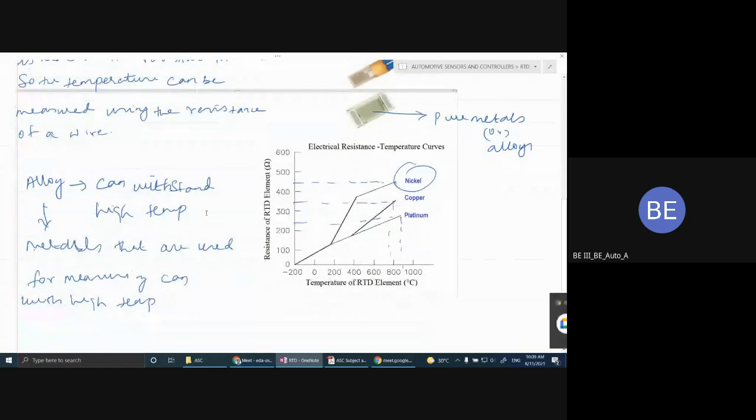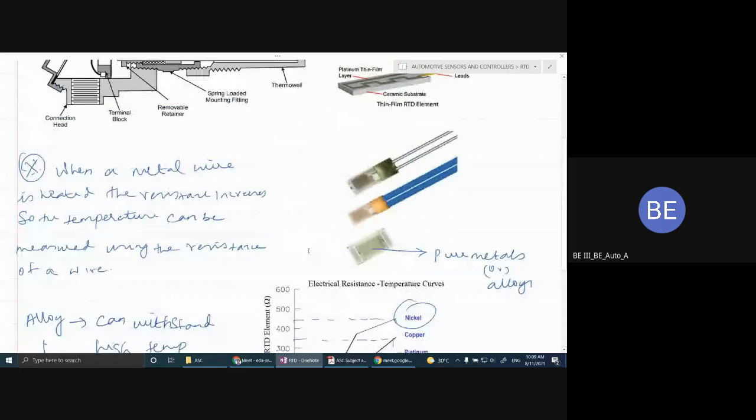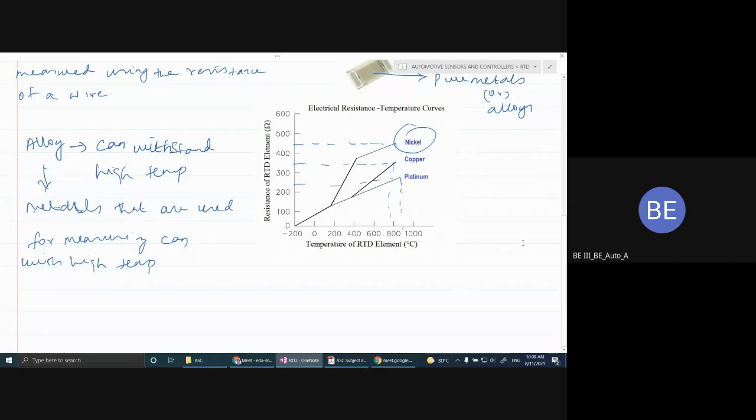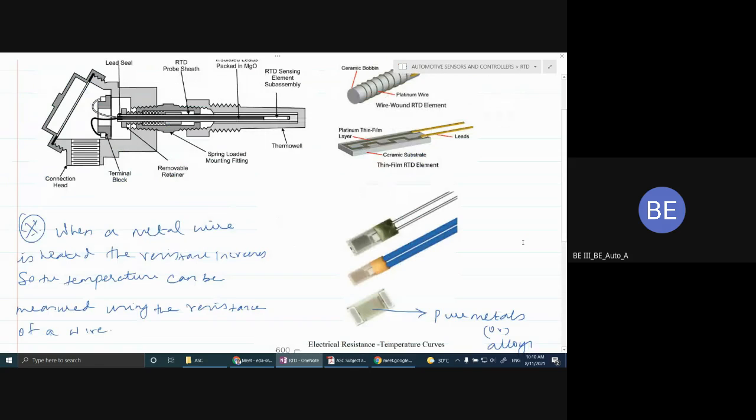Correct. So in which applications may it be used? This is the real RTD, what we are using in our day-to-day activities. Tell me where this RTD is mainly used. Any idea? Microwave oven. Okay, to monitor the temperature inside the microwave oven, we can use this RTD. It consists of two wires with ceramic beads, and here we are using this inconel sheath.